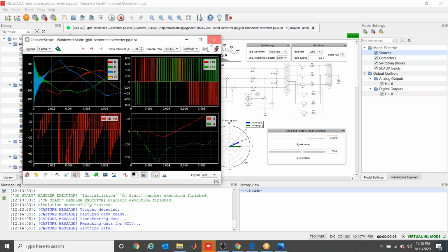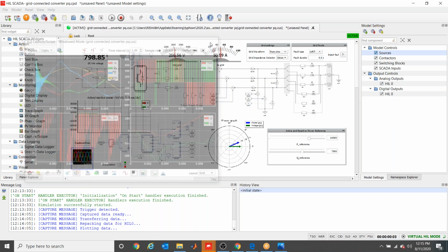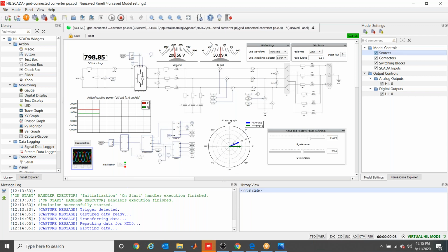If anyone has any query, yeah. Yes, sir. When I'm using the HIL device, my system is very fast, right? Because the whole plant is running on the HIL device, but this scope and all are running on my PC. So will I be able to capture the actual event on this scope, or do I have to use another, physical scope? You can capture the actual data in the inbuilt scope, and if you want, you can also use a physical scope there.